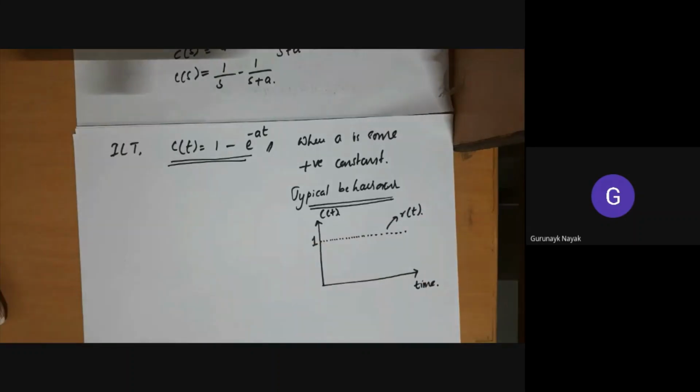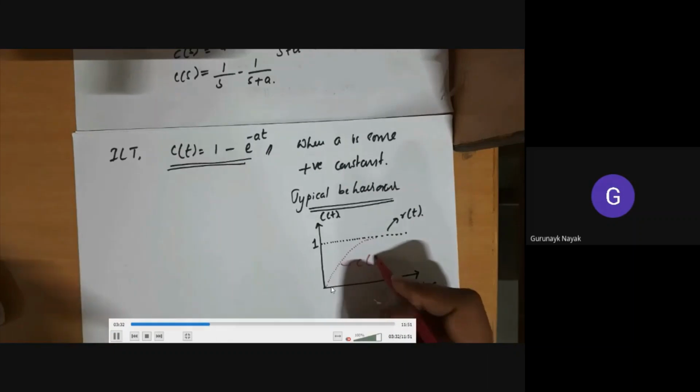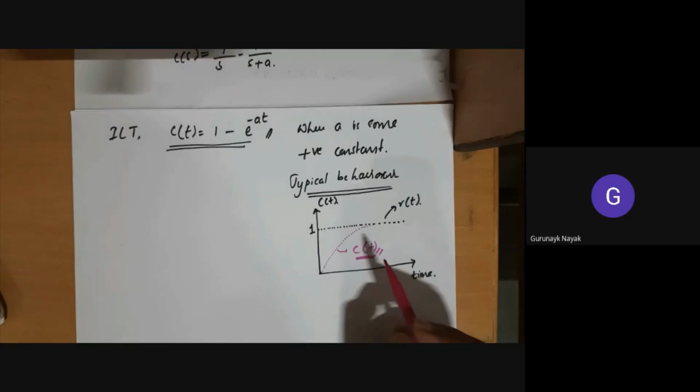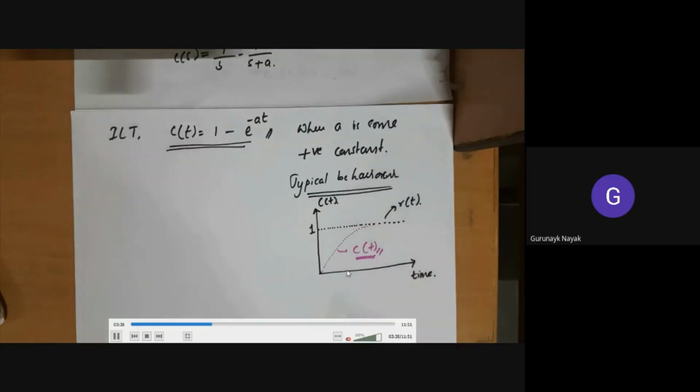So in the same graph, I represent the unit step input, which has a magnitude of 1 and it is called R of t. So my input will always remain unity throughout the time. And for this input, what is the expected approximate output? So this is how you can expect your output. A gradually increasing output. And I term it as obviously C of t. So this is very obvious. Okay. One can judge this for any positive constant A, you end up with this type of graph.